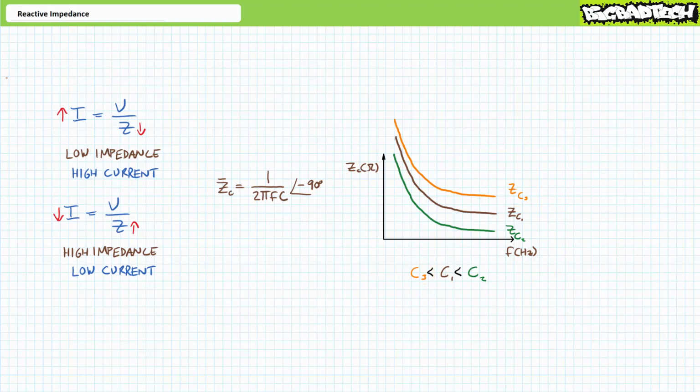All right, that about wraps it up for capacitors. We learned why current leads voltage for capacitive elements and how frequency and capacitance influence impedance. Let's do the same thing for inductors. It's really more of the same, except we're dealing with magnetic fields instead of electrostatic fields, lagging current instead of leading current, and impedance magnitude that increases as a function of frequency and component value instead of decreases. If you want to think about it this way, inductors are the opposite of capacitors and vice versa.